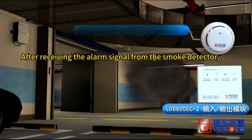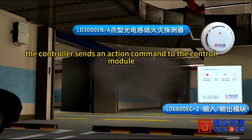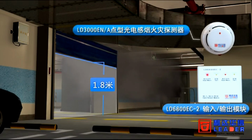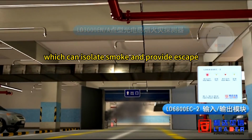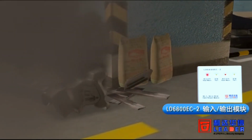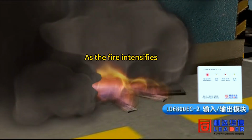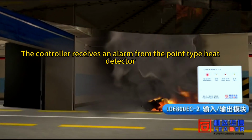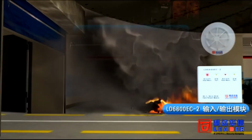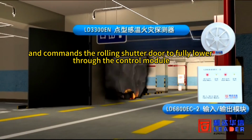After receiving the alarm signal from the smoke detector, the controller sends an action command to the control module. The rolling shutter door is semi-lowered, which can isolate smoke and provide escape. As the fire intensifies, the controller receives an alarm from the point-type heat detector and commands the rolling shutter door to fully lower through the control module.